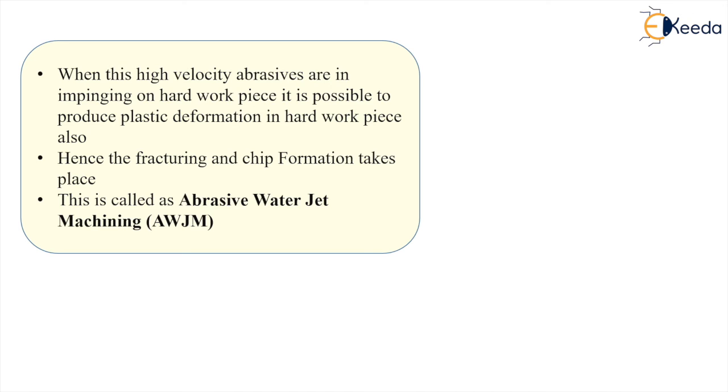Understood? So in this video, friends, we learned about abrasive jet machining. What is the mechanics of abrasive jet machining? The high velocity abrasive grains are impinging on the work surface, causing tiny fractures, and the carrying gas or air is taking out the dislodged small chips from the workpiece.